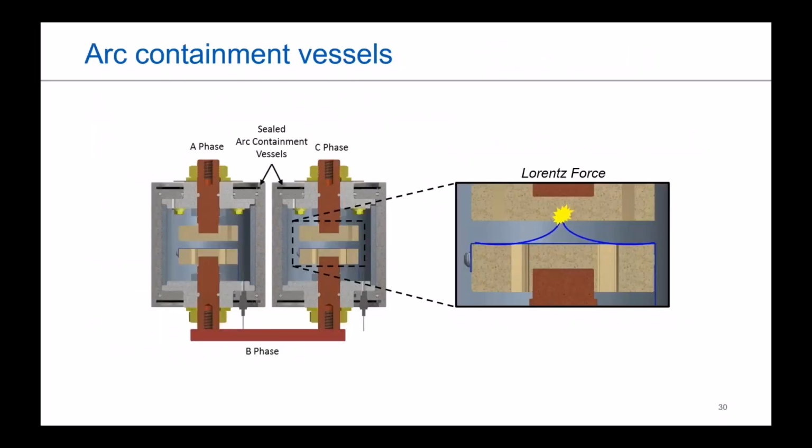When we talk about a quenching device, at least from the Eaton perspective, the way we do it is we have what we call our 2 arc containment vessels, in which the 3 phases are connected up. And then we have a wire that sits across some contacts. The wire itself is run taut. Once this device has a signal sent to it, it'll discharge some capacitors. Those capacitors will then send energy across those contacts.